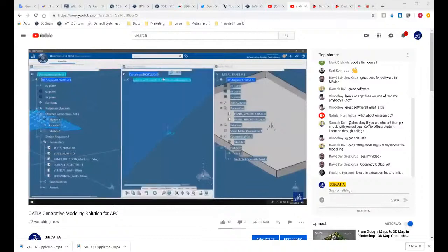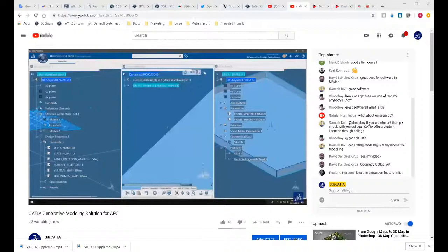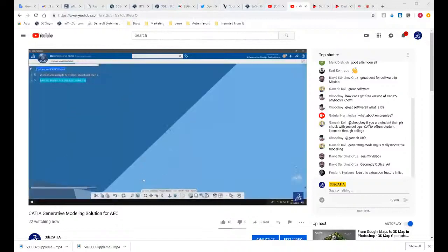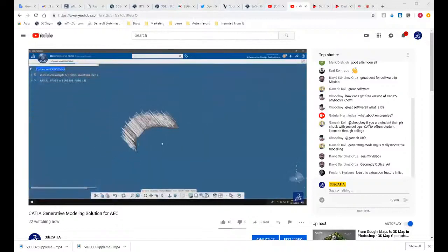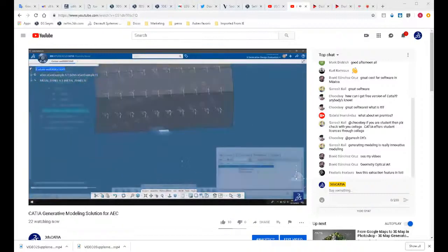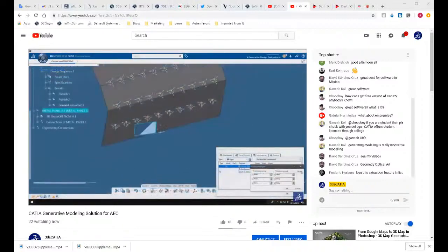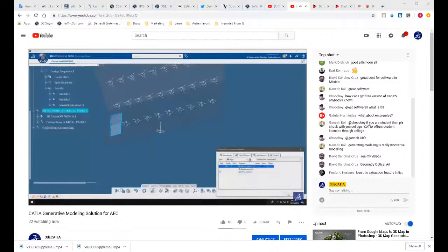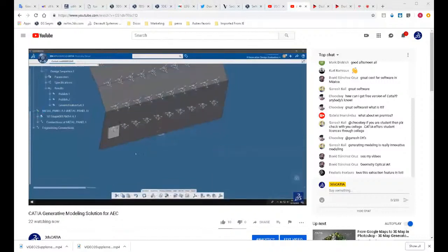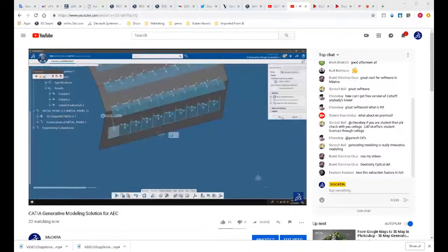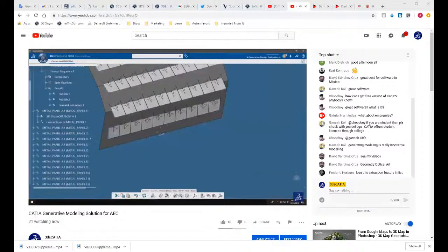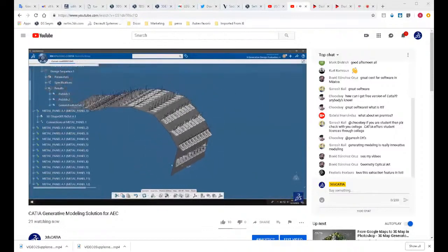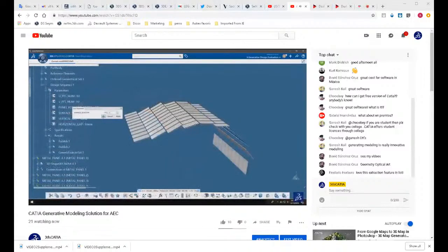And now I'm going to create a CATIA assembly, a curtain wall assembly. So I'll input my X Design and X Generative Design model. I'll input my sheet metal panel, and I assigned the width of the sheet metal panel based on the rectangle sizes from X Generative Design. I can do an assembly constraint to position my sheet metal panel in place, and do an assembly pattern to replicate that panel across all of the axis systems in my model.